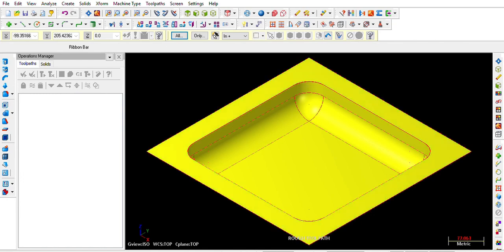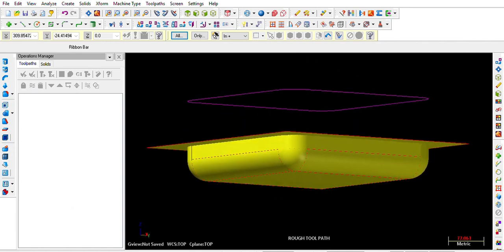Now what I would do is I need to prepare a boundary for this one. So I would transform or translate some of the curves for generating my boundary. Transform, translate only lines, arcs, only wireframe, and the z-axis by, let us say, 100. Copy.